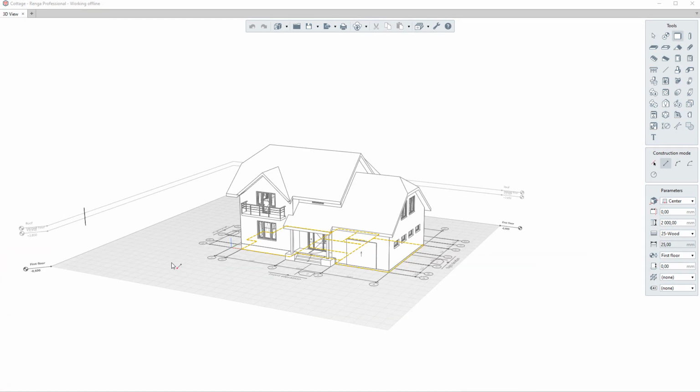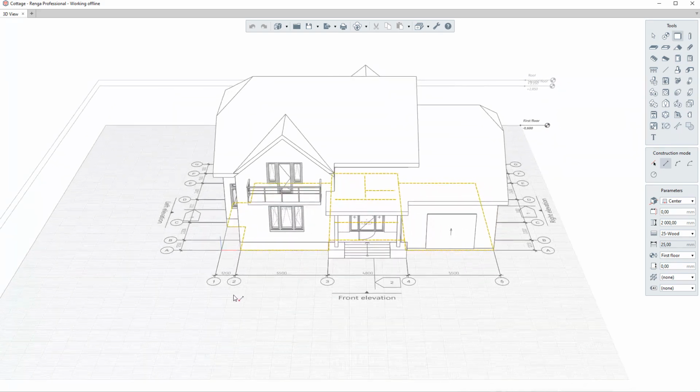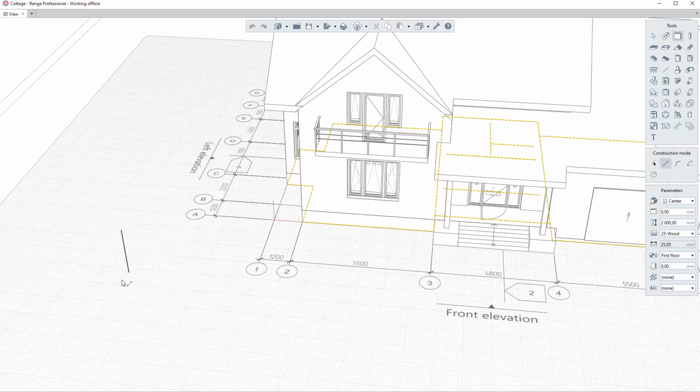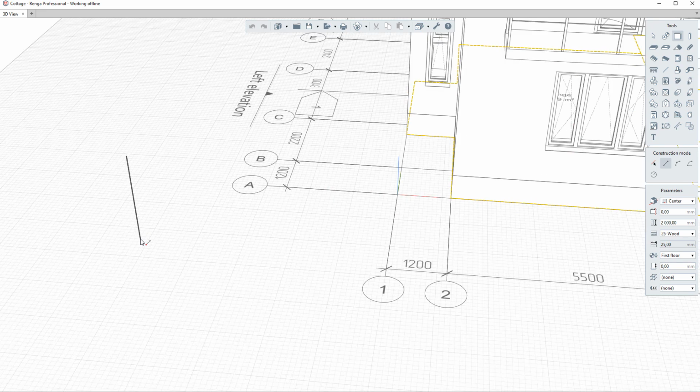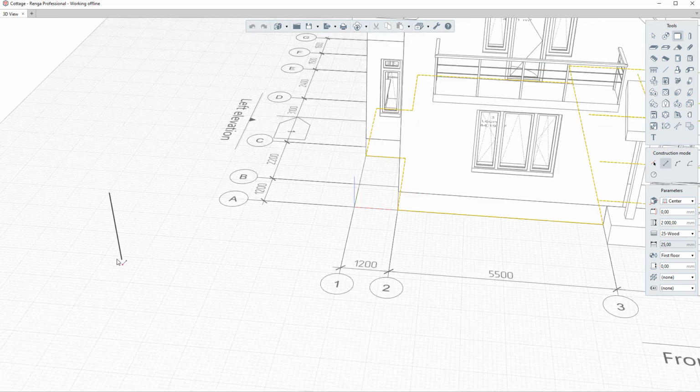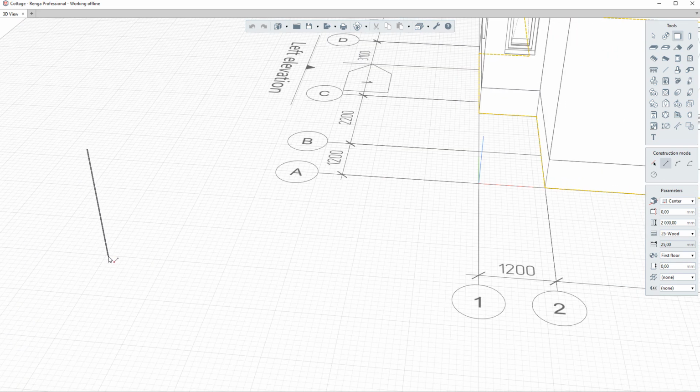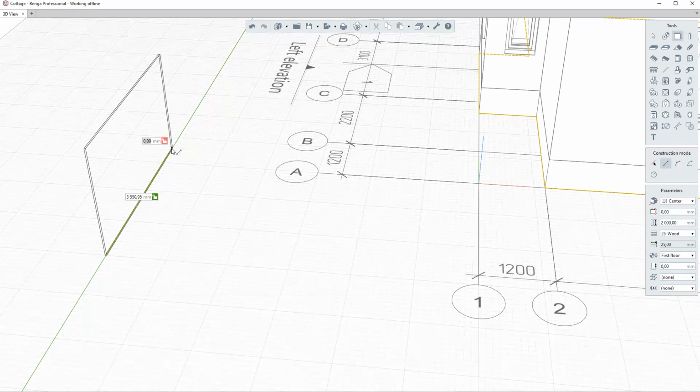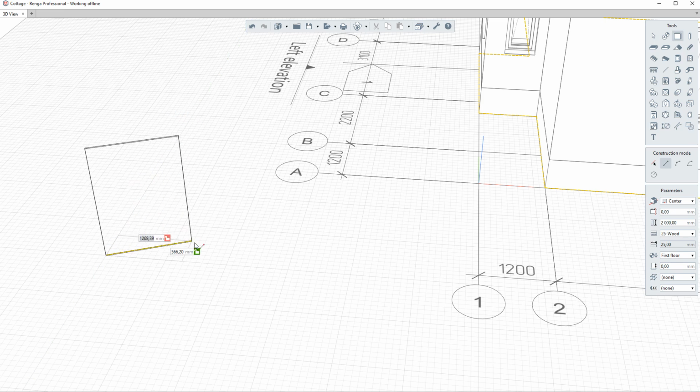Forming up is produced at the model levels where users place the work plane. The work plane is lined with a grid in millimeters. We may use snaps to the grid. For that, press the Shift button and left-click to fix the position when the point appears in the grid node. Move the mouse cursor to the grid line. We see a phantom view of the wall and dynamic input fields. Each input field is displayed on a relevant extension line of an object during construction.